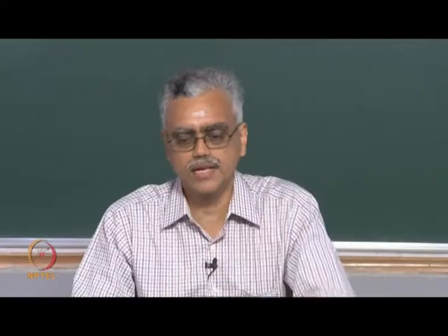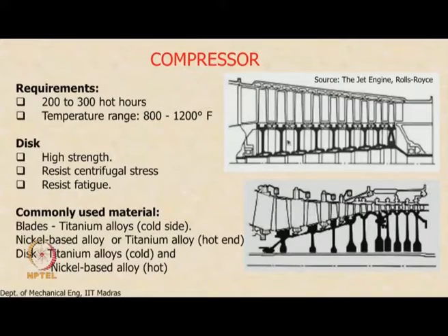Okay. So you can attach the blades in both ways, but you can see that this region between the top of the disc and the shaft is hollow. There is nothing here. This is very important, not only from a weight saving perspective, but also from some other perspective which we will discuss next.